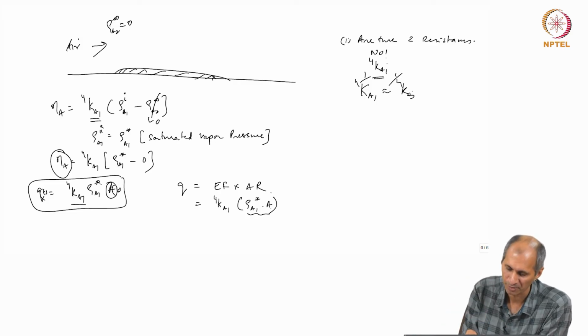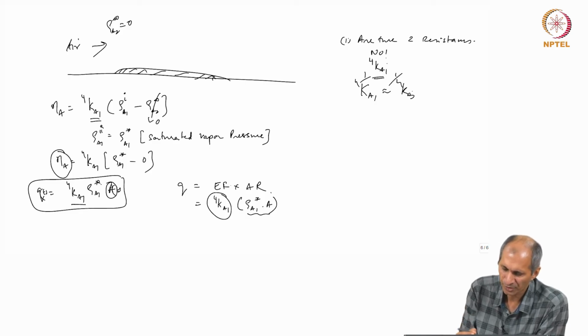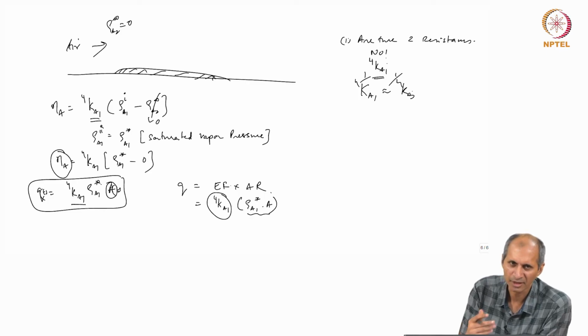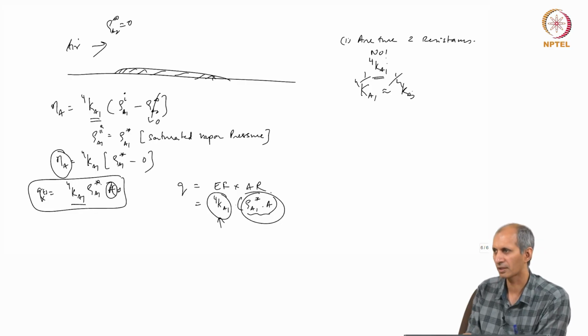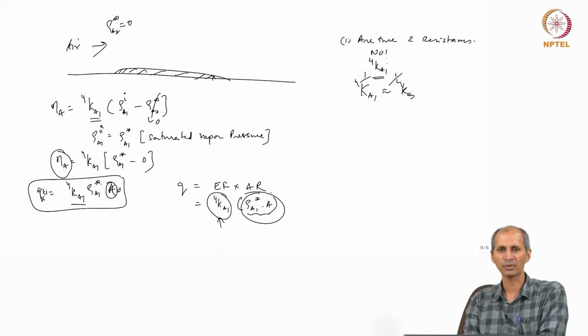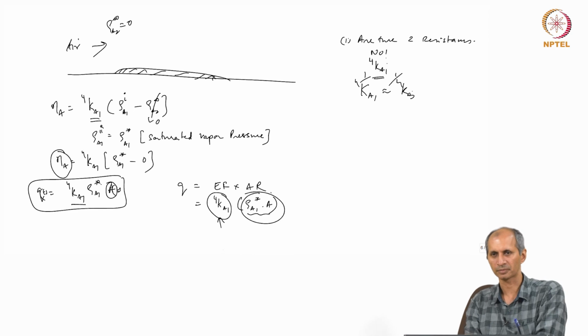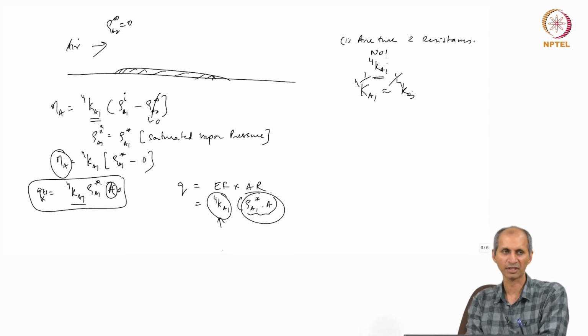If solution phase comes in, then of course this becomes capital K and all that. That changes. So, we do not call it an emission factor, but in terms of what controls and what does not usually change with whatever is here, the mass transfer coefficient, whether it is an overall or an individual mass transfer coefficient, is now the equivalent of the emission factor for these kind of problems, where it is not a specific fixed source and it is dependent on wind speed and other environmental parameters.